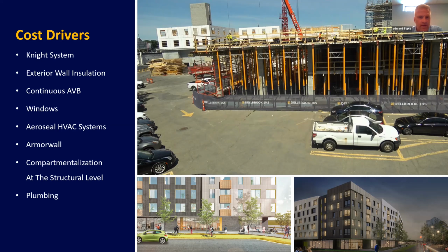Spray all your ductwork to get your duct leakage to a certain point, where, to Evie's point, you can't underestimate the blower door test. You can't underestimate it, no matter how confident the ductwork supplier or the subcontractor is. You've got to insist upon them hiring either an aeroseal subcontractor or being one themselves. We have some HVAC contractors now who are certified themselves.